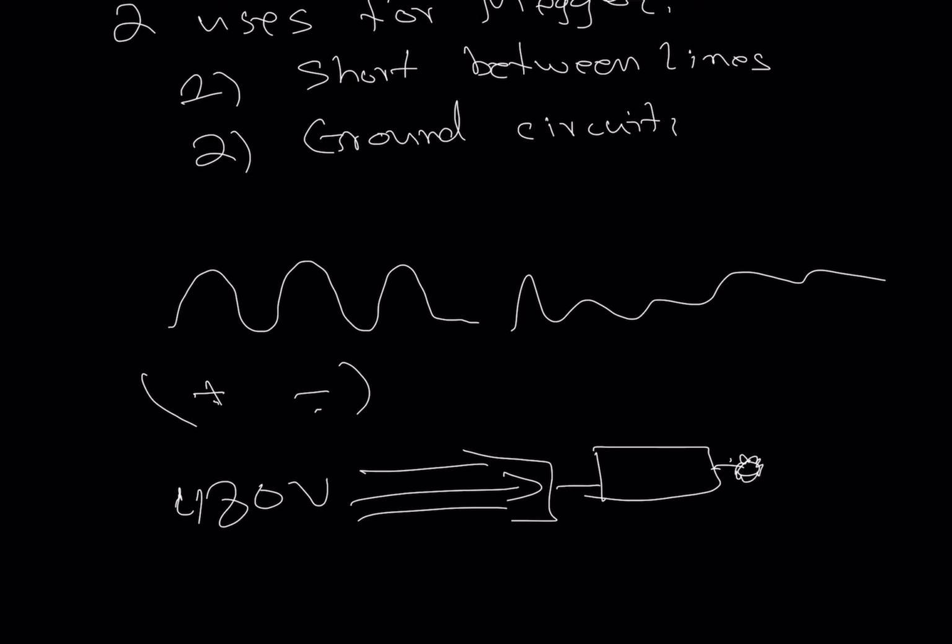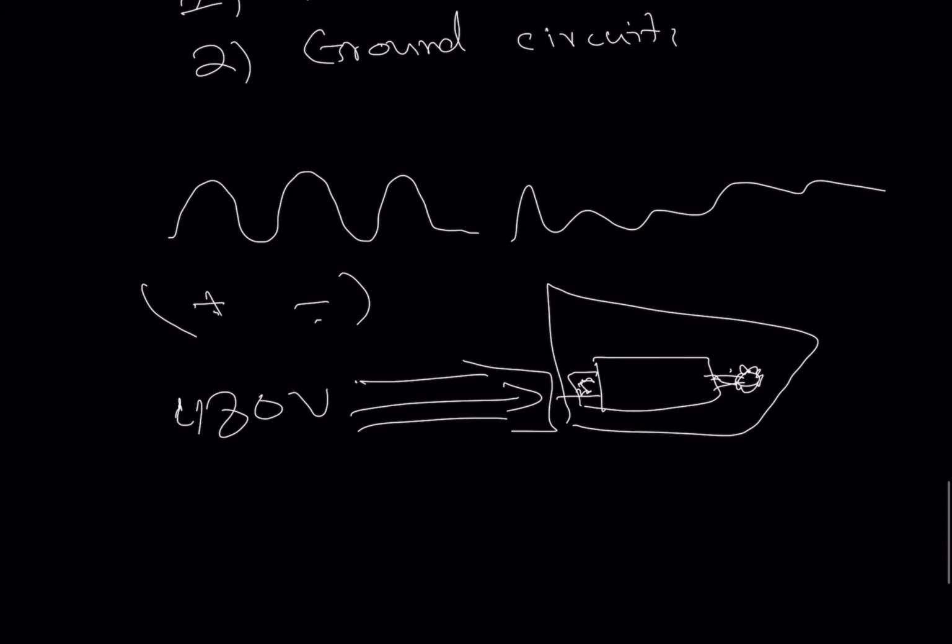This is your junction box for the connections, for the motor, with the power coming in right here. If this motor is, for example, a conveyor motor or an elevator motor, and as soon as you hit the start button it trips the breaker, the first thing is to check the physical condition of the motor, to see if it is hot, burning, or smelling, which will tell you the motor is going bad.